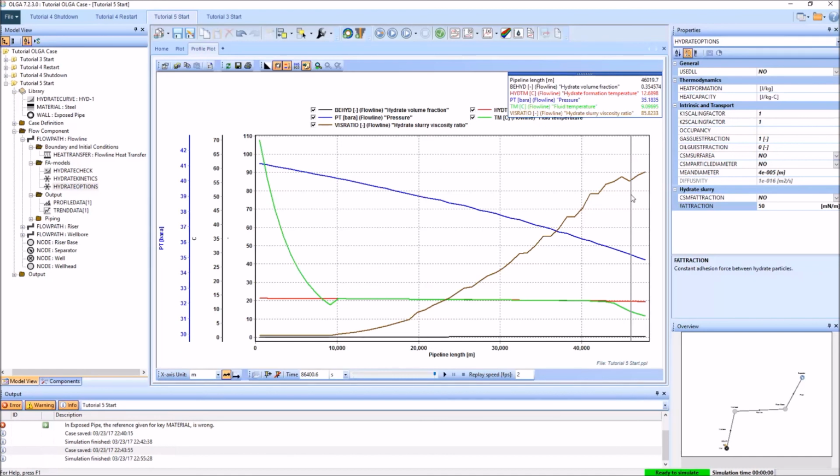Now, is that going to be a sufficient hydrate management strategy? Well, potentially it requires some more experiments to be run. And you also have to think about the effect on flow rate of having a fluid which is now 10 times more viscous than the original. Now, interestingly, if you look at the flow rate outputs from OLGA, you'll see that it doesn't take into account this effect on flow rate of the increased viscosity. So this is something that needs to be kept in mind when you're looking at your OLGA simulations.